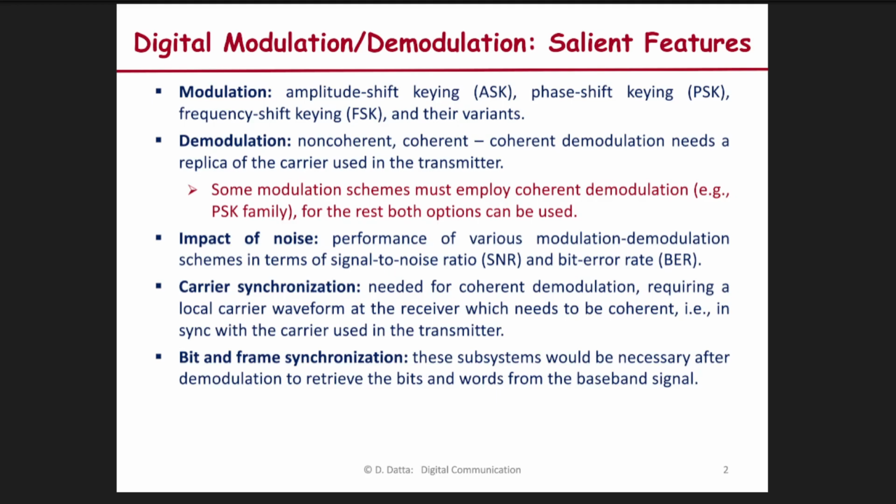You can have a one-sided spectrum, which is cos omega_c t or sin omega_c t, or you can have e to the power j omega_c t plus e to the power minus j omega_c t, by 2. Then it becomes a two-sided spectrum. So I have taken here the two-sided spectrum. Your voice spectrum, suppose, extends from minus B to plus B, in respect of any modulation like analog modulation. And if I modulate by a carrier fc1, then the spectrum shifts. It shifts from the origin and becomes centered at plus fc1 and minus fc1.